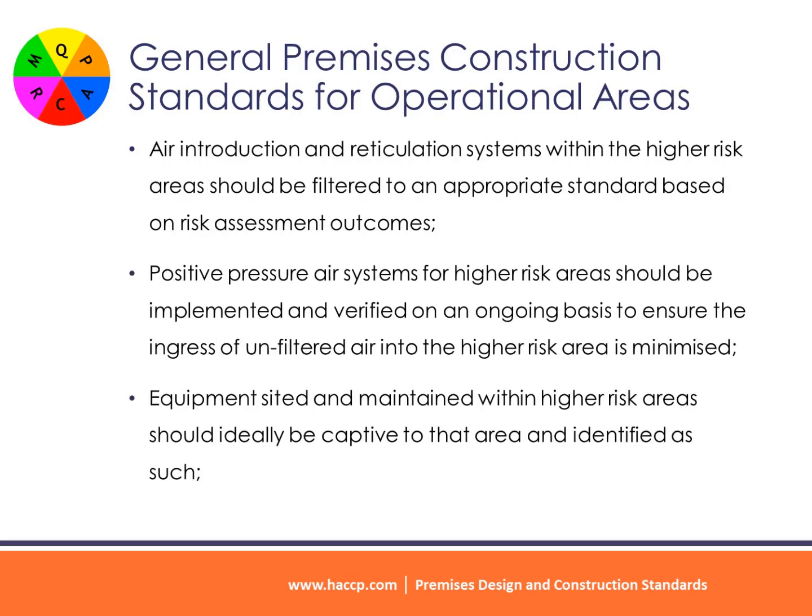Air introduction and reticulation systems within the higher risk area should be filtered to an appropriate standard based on risk assessment outcomes. Positive pressure air systems for higher risk areas should be implemented and verified on an ongoing basis to ensure the ingress of unfiltered air into the higher risk area is minimized.